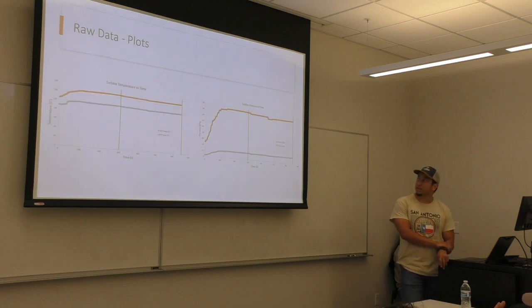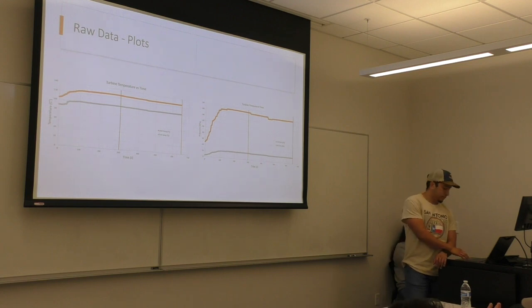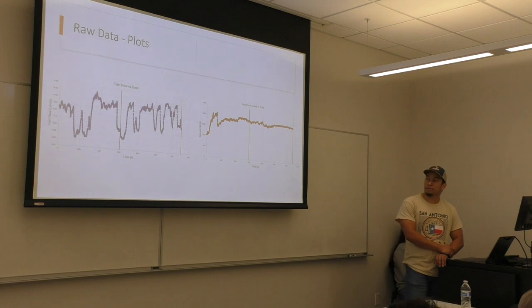The turbines seem to be working fine. The inlet pressure and temperature are higher than at the outlet. That's because pressure and temperature are lost during working conditions. As for the fuel flow versus time and the generator speed, it seemed like the turbine did enough to keep the generator speed constant. As for the fuel flow versus time, that's the fuel flow from the propane tank, and I don't really have an explanation for why it's as sporadic as it is.